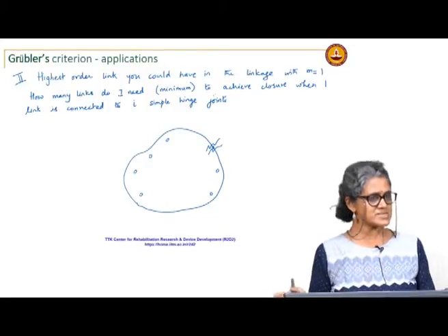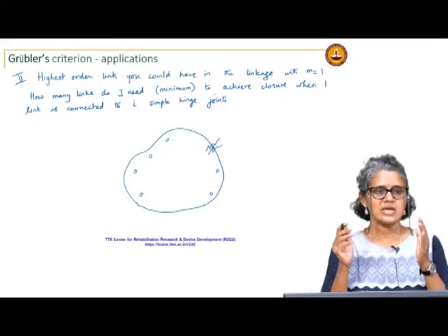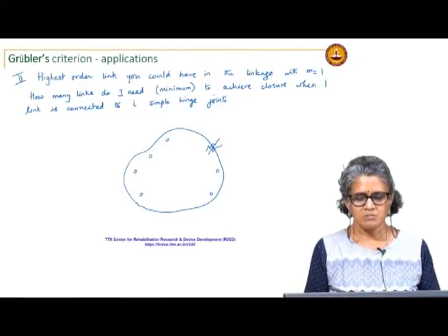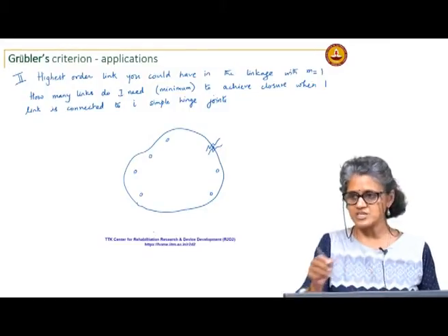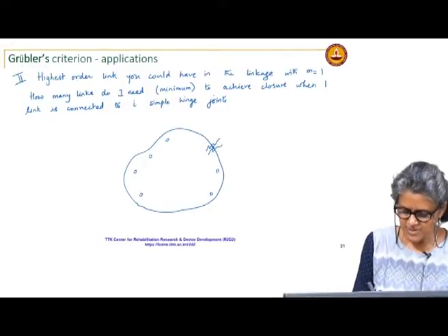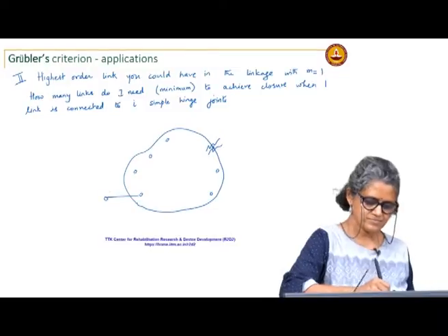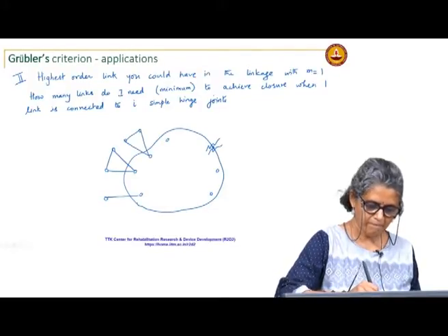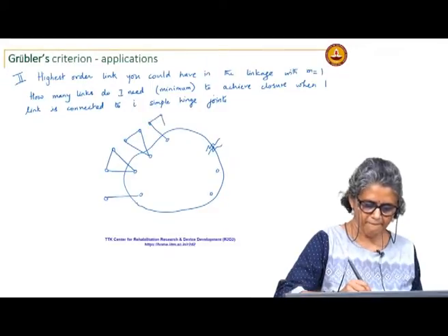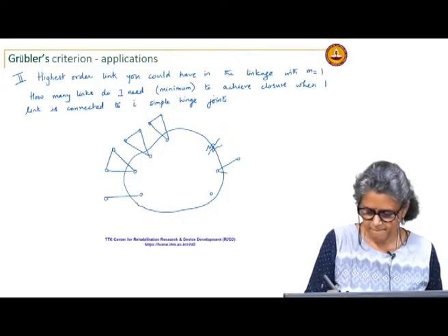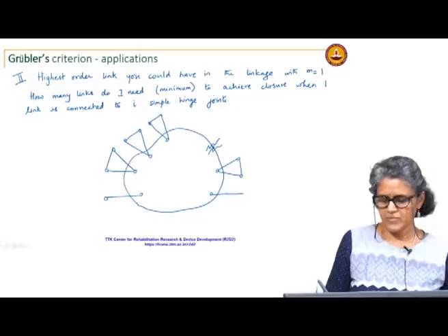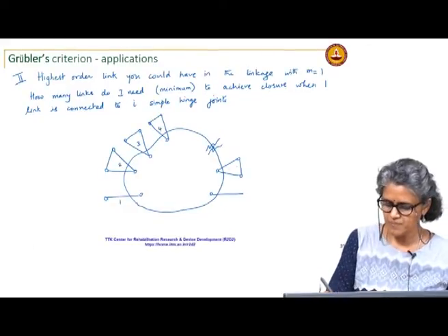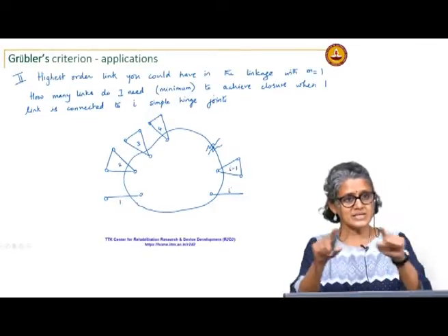Okay. How do I make a mechanism out of this? Basically, I am looking for a closed kinematic chain. If I have one link which has I nodes, what is the minimum number of links I would need in order to achieve a closed chain? So, let us start off with start connecting these to each of the I nodes to links. Okay. So, I start with 1, 2, 3, 4, this is say I minus 1, I. So, these are the links connected to the I nodes.